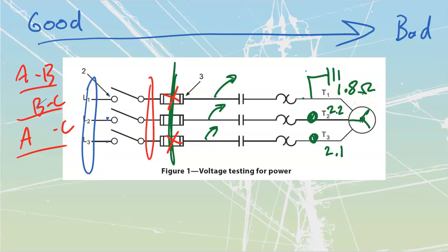The one with the lowest resistance to ground is going to be the one that's closest to the fault. So I would be going through this line with a fine-tooth comb, trying to figure out exactly where that fault itself was. It can be difficult to do: pinched lines, shorted lines. Usually what I would do if I measured something like this is go to the motor, disconnect all of my motor leads just from the motor itself, and then re-ohm this out.